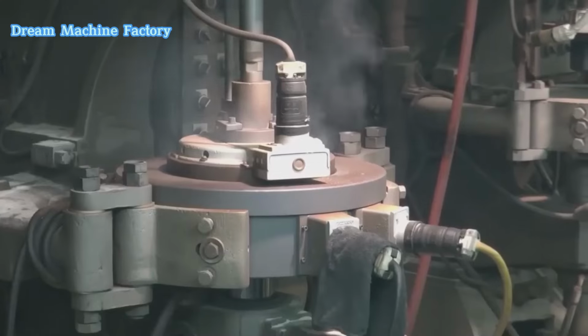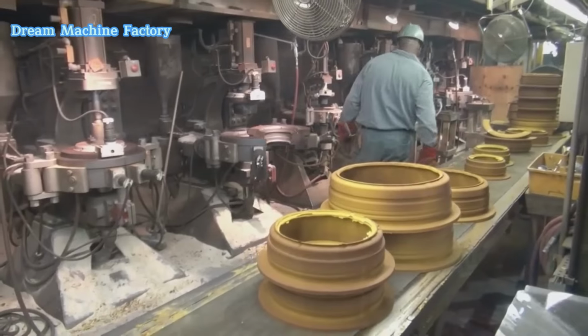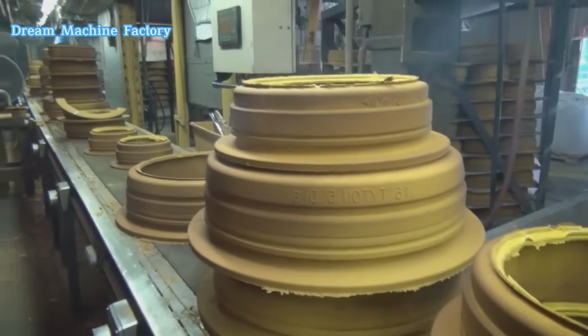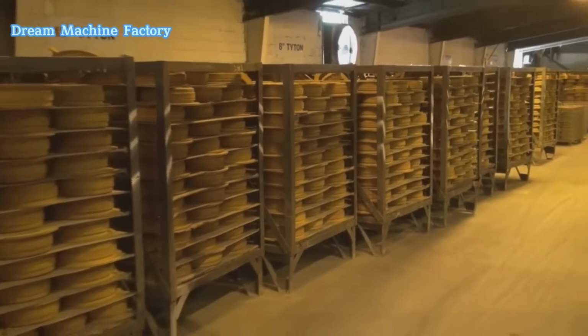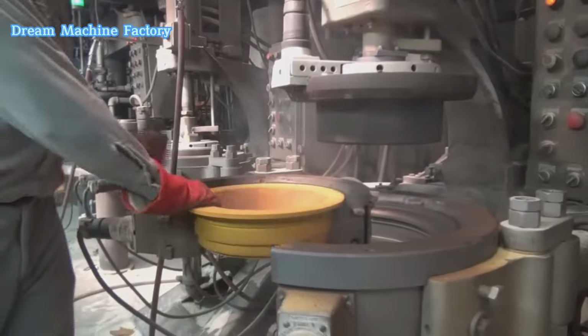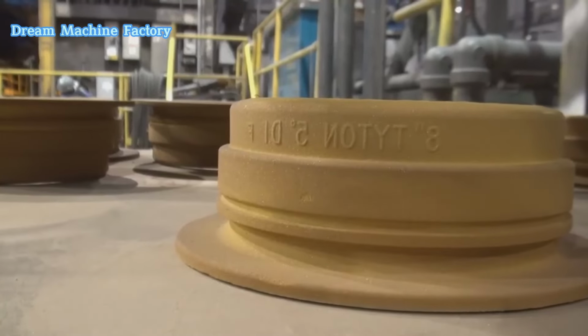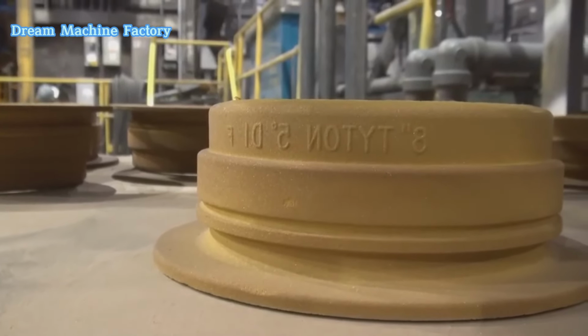The casting machine operator then inserts a sand head core into the bell end of the cylindrical steel mold. These sand cores, made from a resin-bonded sand mixture, help shape the pipe's bell socket where joints will later be fitted. Once the mold is prepared, the pouring ladle tilts, directing molten iron down a chute into the mold's bell end. The mold assembly is then moved along rails as iron continues to pour, filling the entire pipe length.